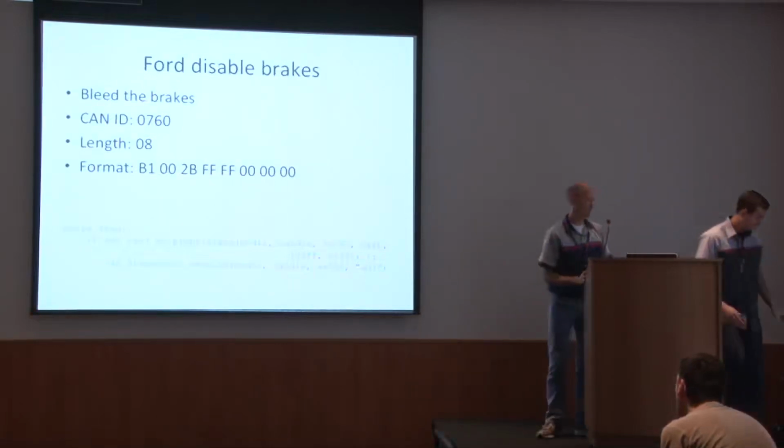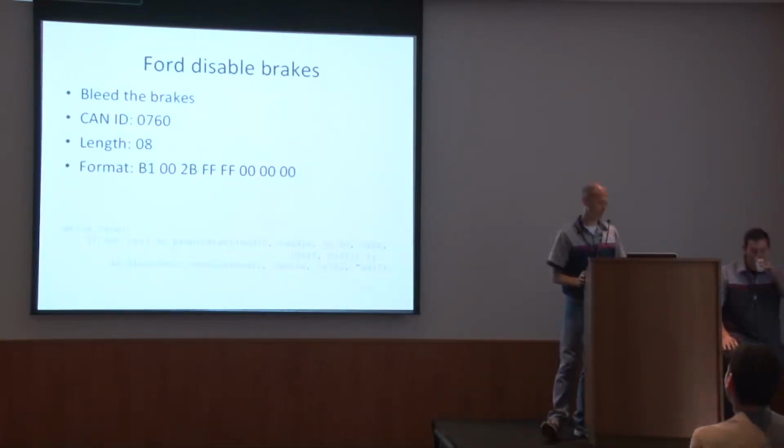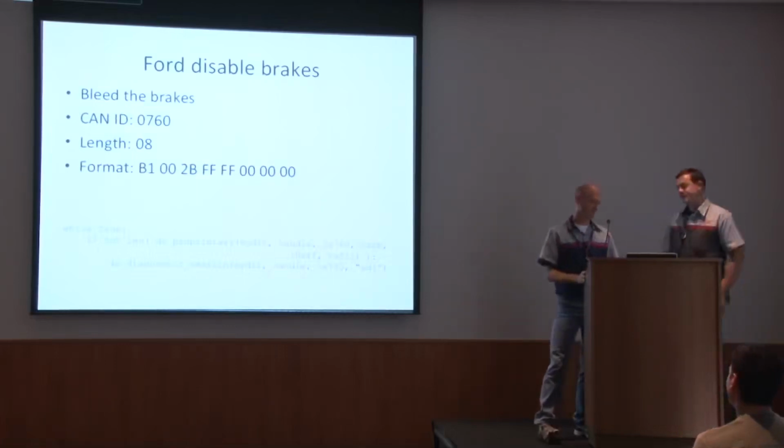So here is the thing that made me crash my car into the garage. It's probably one of the scarier things. It's a command that a mechanic would use to bleed the brakes, to let the air out. So they did build some security into it. It only works if you're driving around 5 miles an hour or less. So if you're driving 40, the brakes still work.